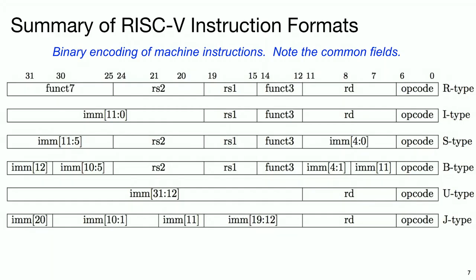Okay, so let me just go a little more on this. We can start to understand how to decode instructions for RISC-V by looking at several different types of instructions. Each type really says how to interpret the instruction. If we identify what type of instruction it is, then we know how to interpret the various fields of the instruction. All the instructions are represented as 32 bits, but what each part of the 32-bit word means depends on what type of instruction it is.